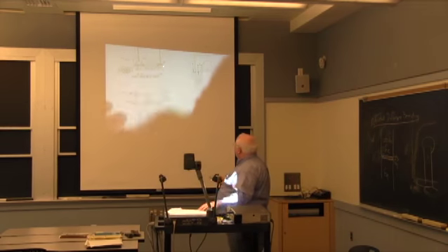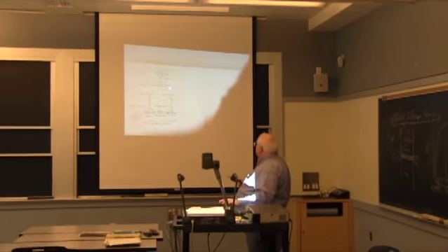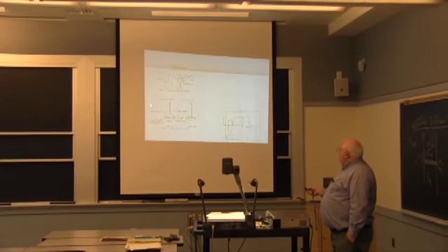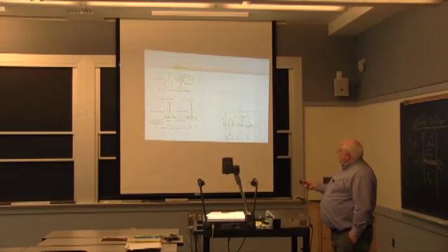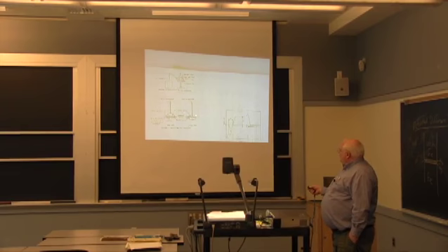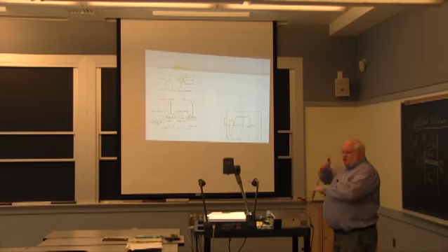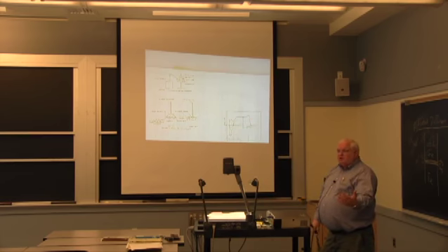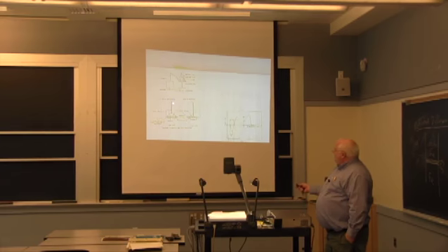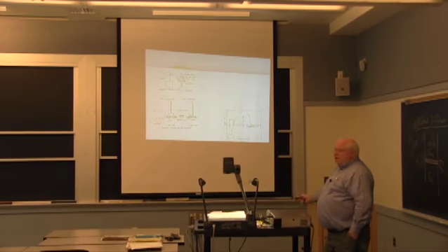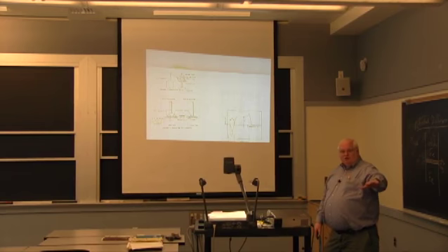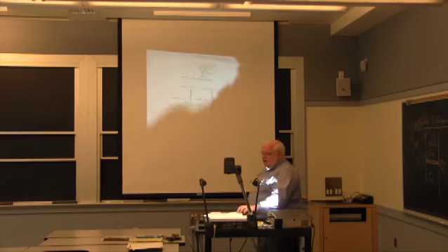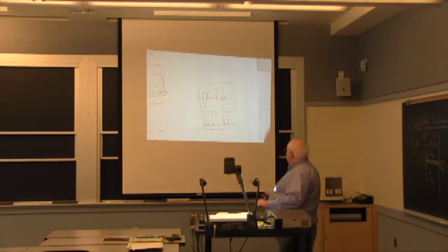Now, there is the automated dip test schematic, where you basically have your whole thing on a rotary dip. You take your circuit board and you basically have a pendulum and you swing it spring loaded, so it goes swinging across the surface of this liquid solder bath. And then you look at it and see, did all the joints get made in the amount of time? And depending on what you have for dampers or springs, you can change the amount of time on your solder bath that it actually is in contact with the solder.